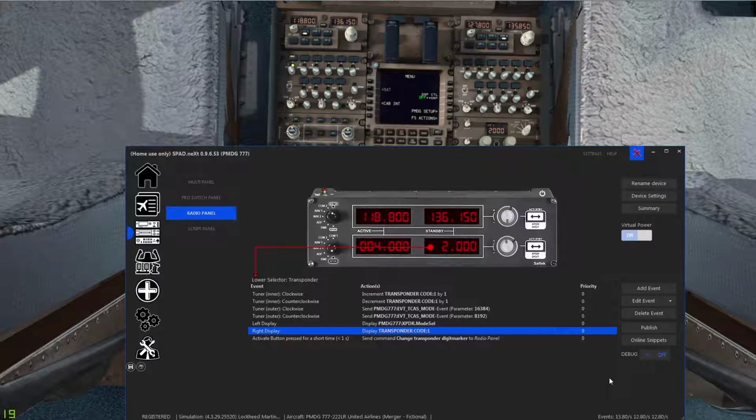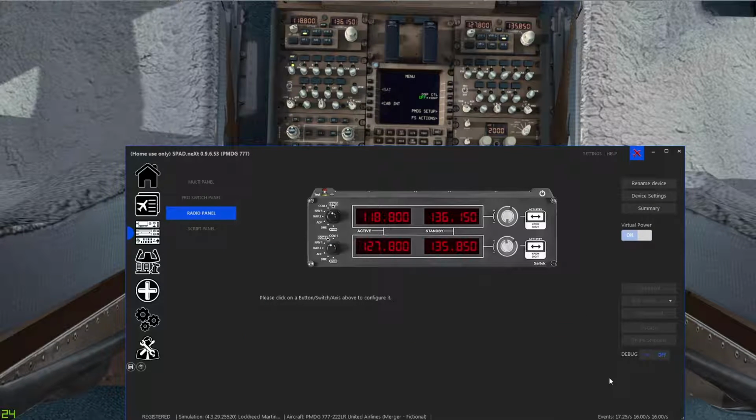Now, the biggest problem that does happen, and we've seen it pop up a lot, is people will talk about how, for example, if I go to COM 2 here and I change that COM value, so I go to 132.85, and when I click that take, you'll notice it jumped back to 127.8. Even though I set it up, it's not actually taking, and it's because this has some intelligence related to the audio panel.